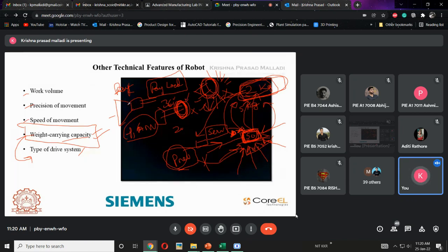Now, if I use this servo type motor or DC motor for this robot, what will happen? Will I be able to do this application? If it is a large motor, maybe it can do this application for one run or two runs, but not for 100 repetitions, 100 turns. Why? Because the motor also works with the same principle. There will be some gears involved in it. Because of the high payload, there will be a huge load on the meshing gears. Because of this, there will be continuous wear on these parts, so this will also fail.